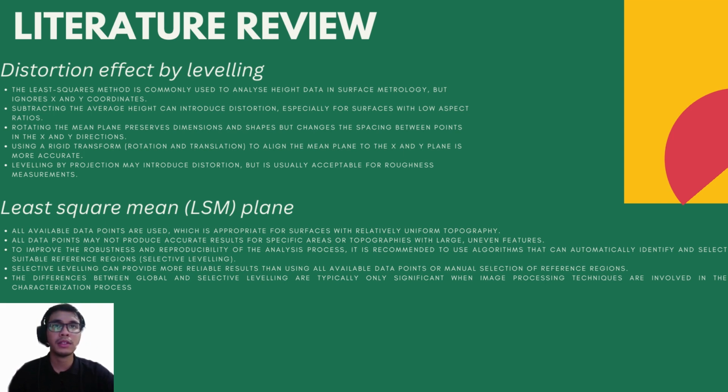Other studies suggest computing the least square mean plane using all available data points in the surface topography, which is known as global leveling. This is typically appropriate for surfaces with a relatively uniform topography, but may not be suitable for analyzing specific areas or for topography with large uneven features such as protuberances or indentations that are asymmetrically located. In these cases, using all the data points may not produce accurate results.